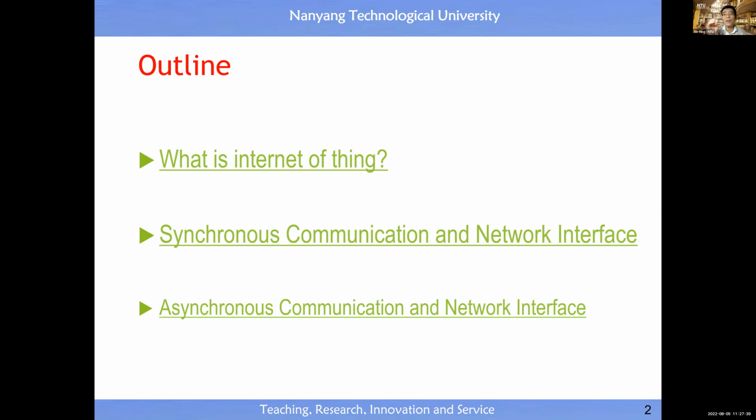In lecture 2, we studied synchronous communication with hardware support to synchronize the byte-by-byte communication, because communication at the bit-by-bit level is always synchronized. But when we communicate data, conceptually the basic unit of the data is a byte, not the bit, and only the hardware implementation is at the bit level.